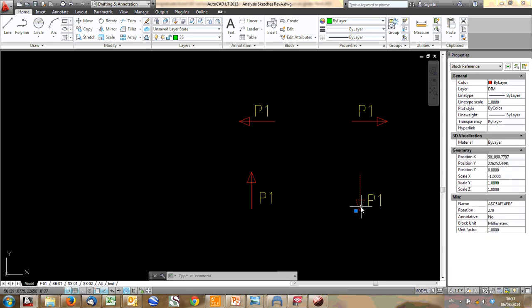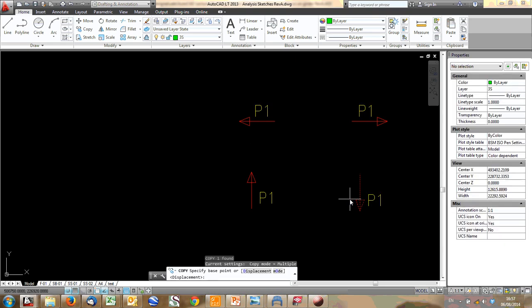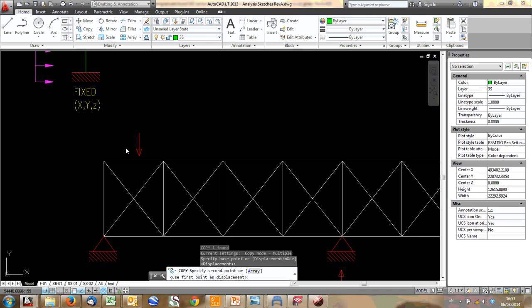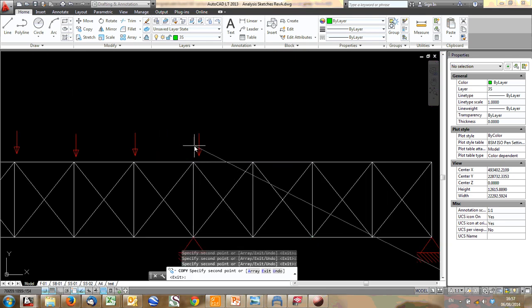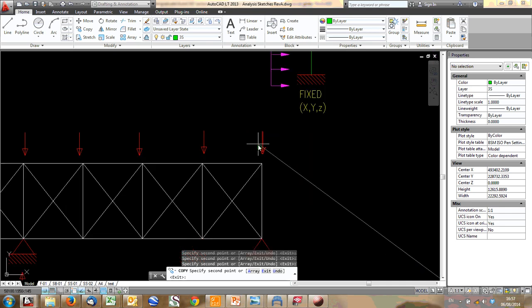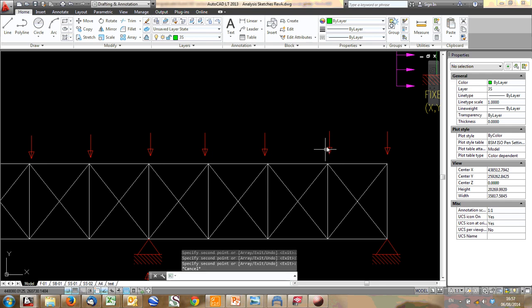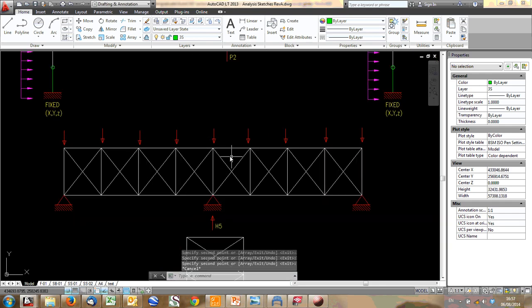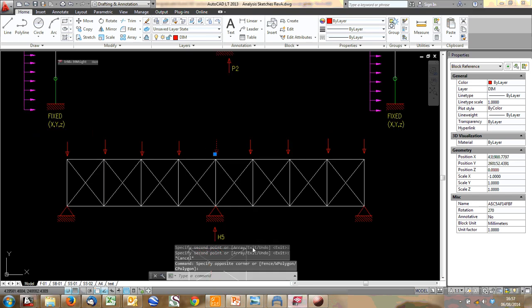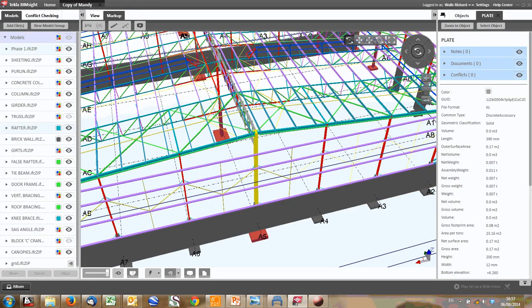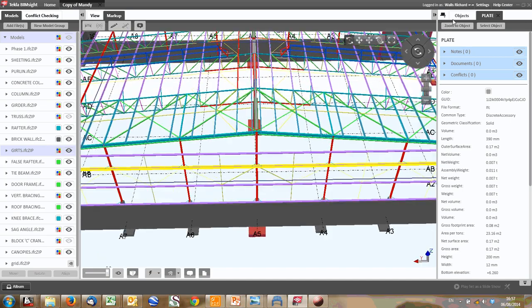If you've got all your loads coming down from your gable columns on top of it, let me show you that. So you've got all your gable columns loading this structure, or you could possibly otherwise put a UDL. But with these long spans, it starts getting a little bit more difficult to do that. You can analyze this one. Just be very careful if you add this one in. Don't double count it, so that you then go and add it again when you analyze this model, or you leave it off the model and then you add it separately as a UDL on this column.